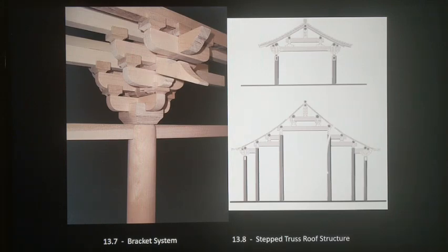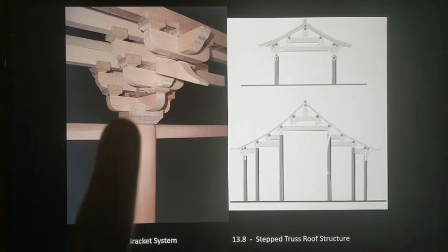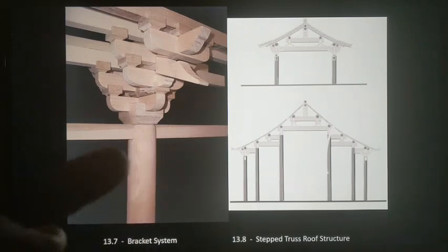So when we see this example here, you have one vertical post, and then on top of it, the capital really is a perpendicular arrangement of brackets. The wood is stacked, and as it moves upward, it starts to expand outward. So you're increasing the surface area that is supported and then passing efficiently all of that force down to the ground through the post.